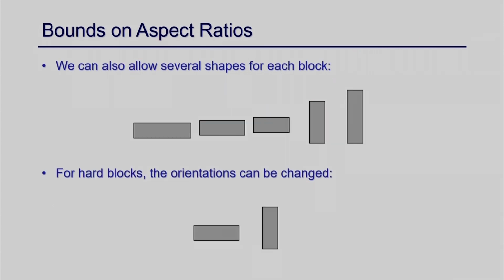So, as I mentioned, for the same size you can generate different kinds of blocks, right, and the orientation may be this way or that way. So, you have to consider all possible orientations given the aspect ratio constraint, and then you try to place all those blocks in the area. Your primary objective is to reduce the area size, so that you can place all of them in the smallest possible area, right. This is floor planning.